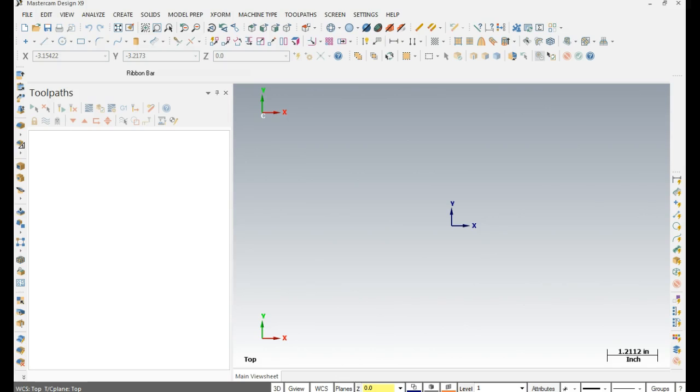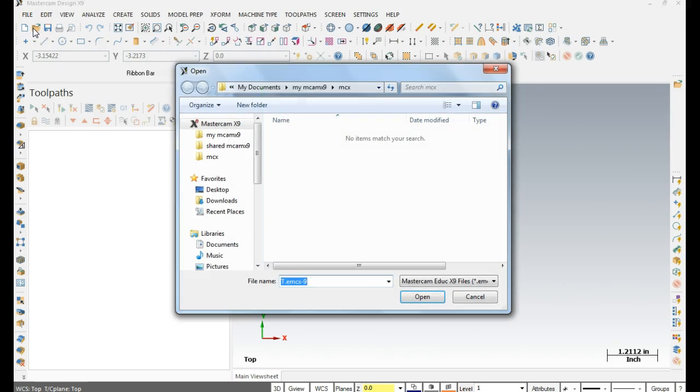I did have an issue. I have an old version of Inventor, and I had trouble getting the Inventor part in as a straight IPT part. But you can always convert it to a step file, and a step file is the best because step files do solids. You can convert it to a step file, then you can read it directly. So to demonstrate this, the first thing we're going to do is read in a ProE part, which is of course now Creo, but it's ProE.